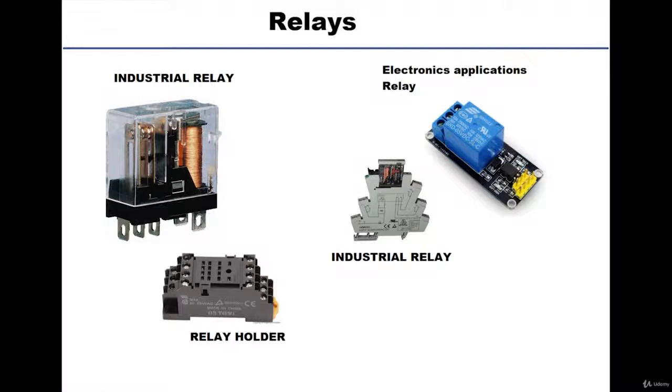So, at least for nowadays designs, relays are used as a buffer between the actual actuator and the PLC. To protect the PLC from different hazards that may be caused by the equipment in the machinery, we use relays as a buffer and a protection layer.